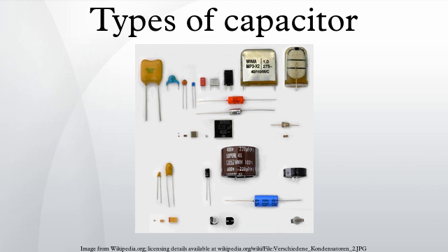Capacitance, tolerance and date of manufacture can be indicated with a short code specified in IEC EN 60062. Examples of short marking of the rated capacitance: μ47 = 0.47 μF, 4μ7 = 4.7 μF, 47μ = 47 μF. The date of manufacture is often printed in accordance with international standards.